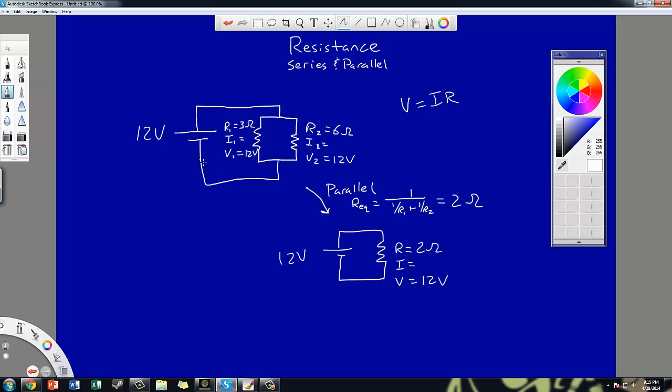If you are an electron traveling through this circuit, you can only make one choice. You can either go left here and go through R1, or you can go to the right and go through R2. But in either case, as soon as you get through that resistor, you're now on the other side of the circuit. You're essentially at the other side of the battery, and so you've gone through the full 12 volts. So when I came here and found the 12 volts, I didn't technically have to do this. I could have jumped right to the voltages here.